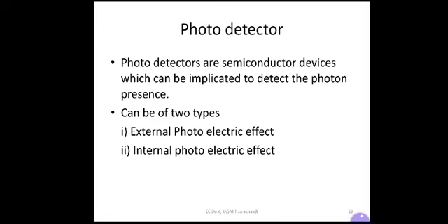There are a few important detector properties that we can list, that is, the features of photodetectors. They are the responsivity, spectral response and response time. Responsivity is the output current divided by the total light power falling upon the photodetector.